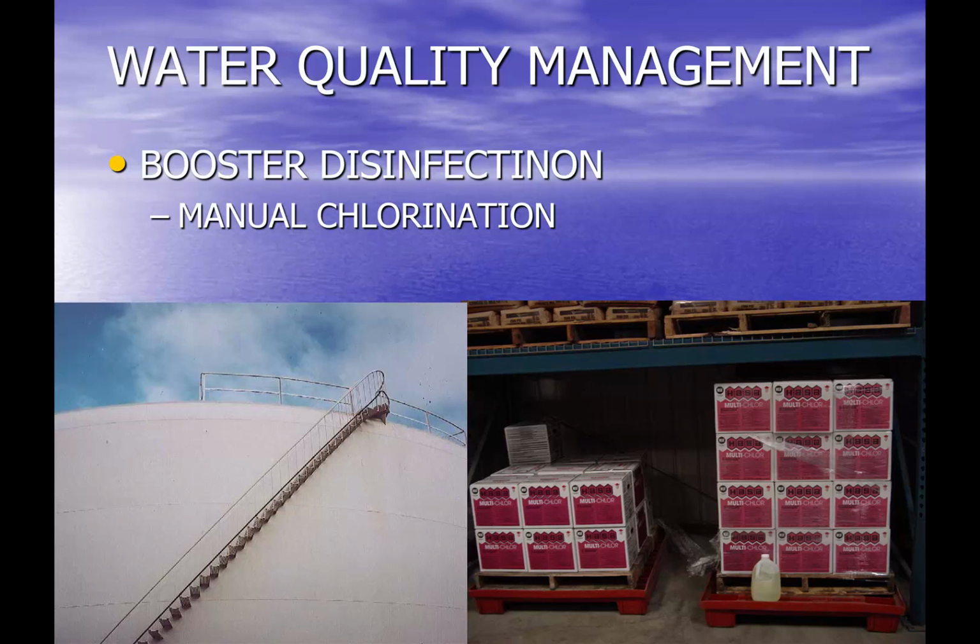You're getting a pretty concentrated amount of chlorine where it hits the water. It's not mixing real well, and we're basically adding chlorine directly, so it's essentially free chlorine, which can contribute to disinfection byproducts. So we're trying to accomplish the objective of resolving a declining chlorine residual, but there are some downsides with that approach.